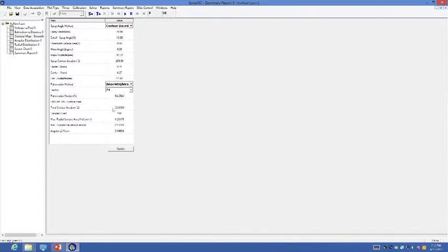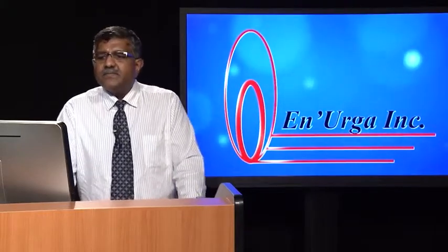You can see the total surface area, which is very important. The higher the surface area you have in a spray, the more intense is both the combustion and evaporation that you can get from that particular nozzle. So, if you have to select among different types of nozzles for a combustion application or a spray drying application, choose the nozzle with the highest total surface area.